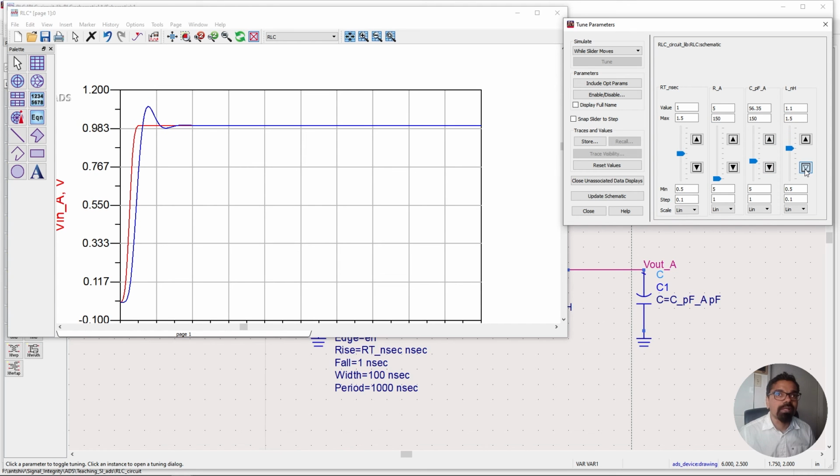Now, clearly, I am trying to make my judgment based on the simulation parameter itself, but you need to do it the other way around. Now, what does the rise time have to do with all of this? What if I decrease the rise time? Will the overshoot decrease or will it increase? So let me try to decrease the rise time. And now you can see that the overshoot is actually increasing. This overshoot is not drastically increasing, but it's increasing as I'm bringing the rise time a lot smaller. So what if I make the minimum, say 0.1 over here, and then keep decreasing this?